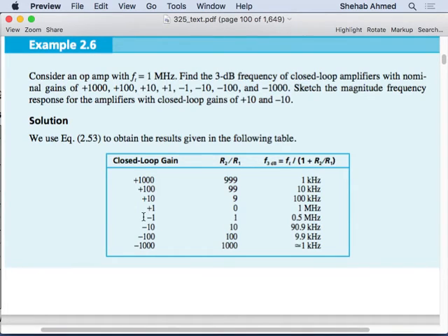The reason is the low-pass filter characteristic of the op amp that you're using. You have a low-pass filter characteristic, which means there's a capacitor in there in parallel, right? If you want a large gain, remember the time constant is going to be what? Probably very large. If the time constant is very, very large, what does this mean? It takes a lot of time to process a signal. It means that the signal that you can process will be limited to low frequencies, right?